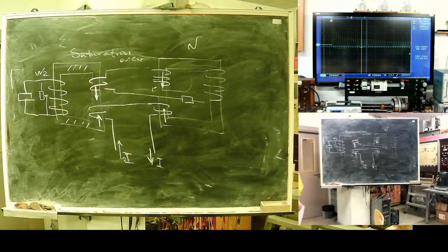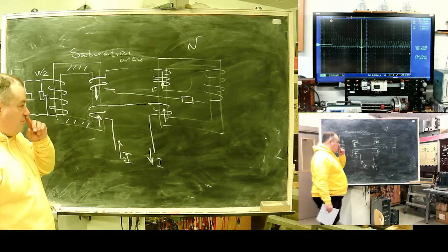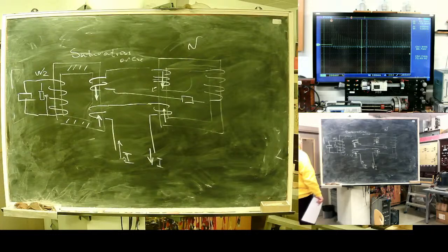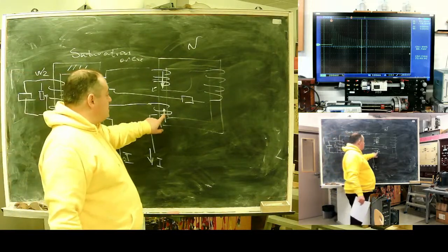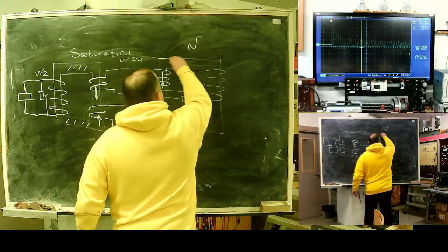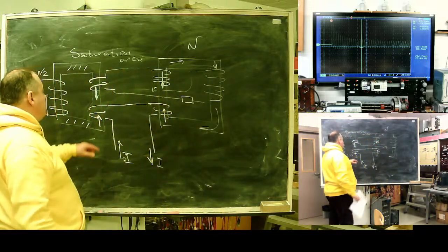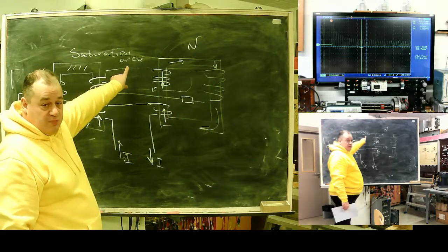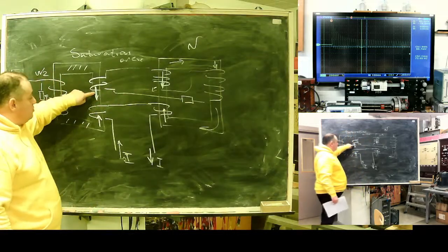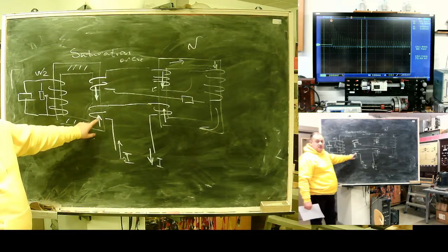See the idea. Assume we have normal regime, no exponential components, current just flowing. If current is just flowing, what will we see? White flux comes this way, transforms, and as a result, here in the loop circulates current induced by white flux, and this current produces blue flux directed against our white flux from the differential current.